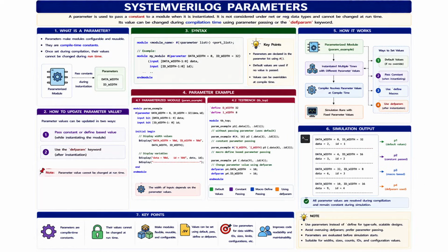The next topic is related to packages. Packages means grouping. It is like a container class. In your test bench, the driver, monitor, scoreboard, generator, and agent are all written somewhere else. I want to utilize them in my same module, so in the top module we will execute all these things. Then I will write one package. In that package, all the signals and all the classes will be included.